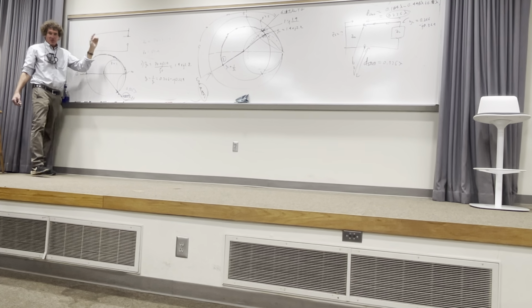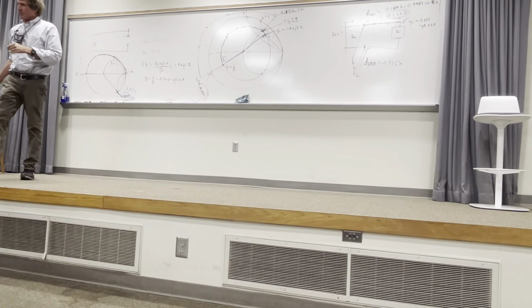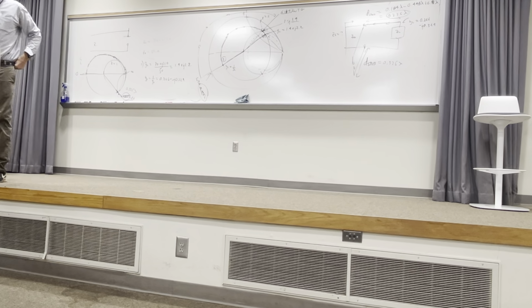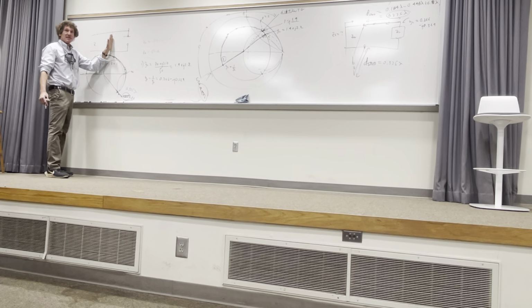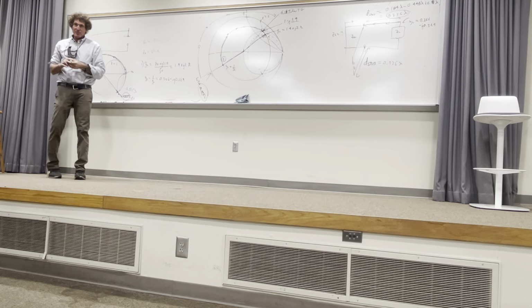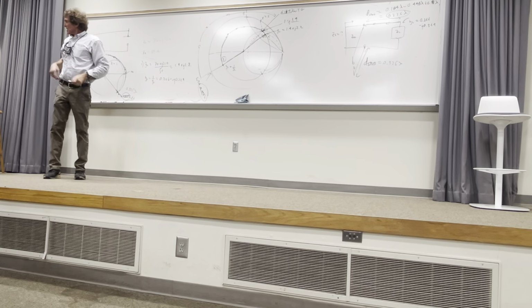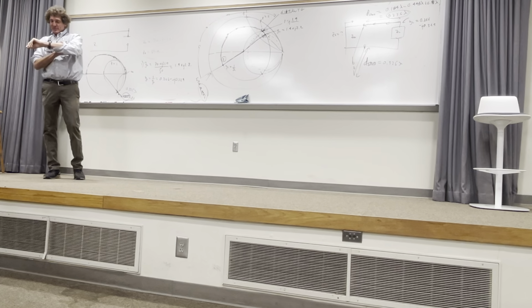Infinity, right? One plus the magnitude of the reflection coefficient over one minus. But that means that on this there will be absolute voltage nulls, and then there will be voltage points where the voltage doubles. But I don't want to spend a whole lot of time on some of these subtleties. It's important to be aware of this. On a stub, everything's reflected. There's nothing absorbed. It doesn't absorb energy. Okay. Any other questions? That was a good question.